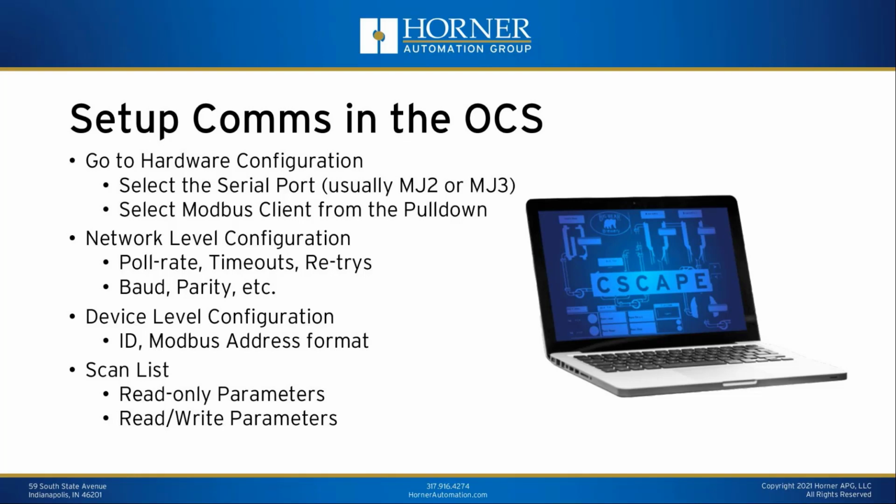You're going to go and do some configuration of that Modbus protocol on the OCS side. First of all, at the network level, adjusting pull rates, timeouts, etc. Again, I'll cover this all for you live here in a minute. You're going to have some device level configuration. For this, each drive that the OCS is talking to, what's its ID? What format is its Modbus address in to make it easier on you to enter in parameters?